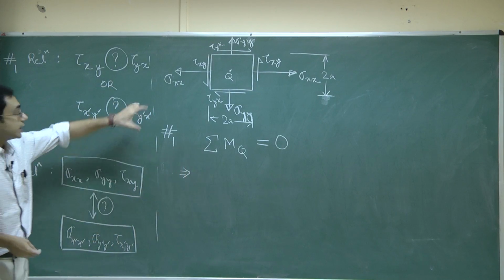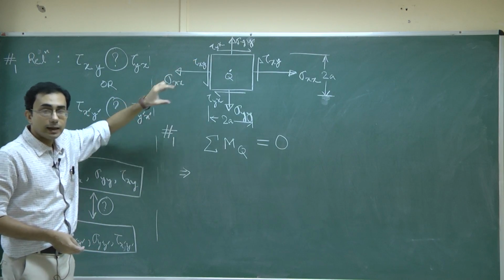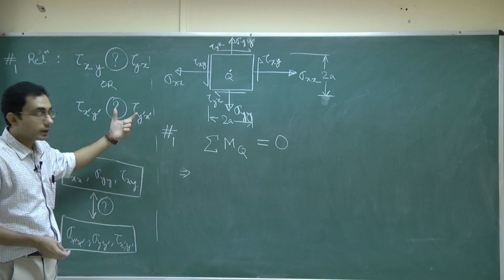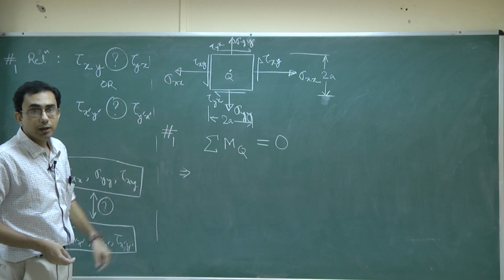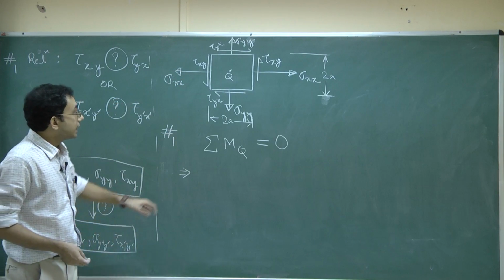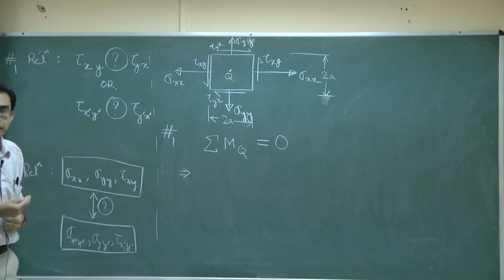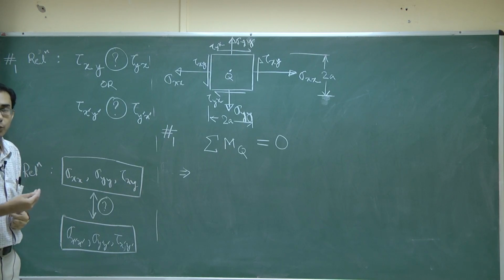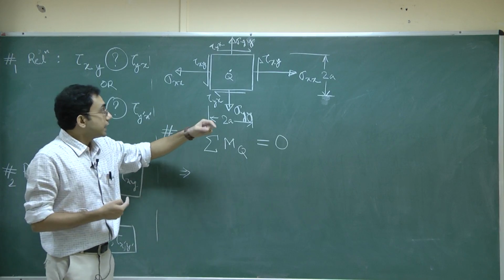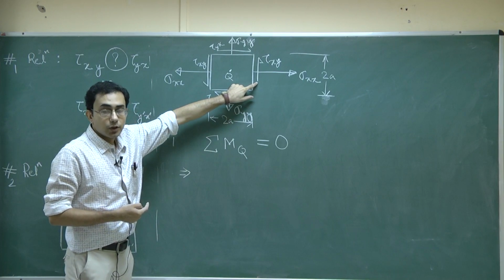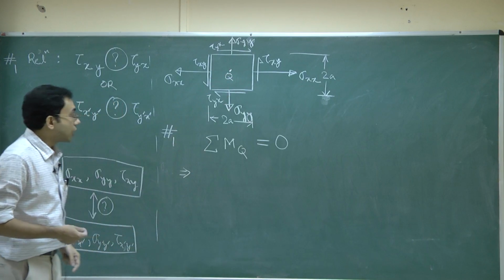Now you note that when I am considering this kind of a little square, which usually is referred to as a stress element, we might as well have called it something else, but we all call it a stress element. Nowhere here are we actually depicting a force, but you understand that each of these stress components is obtained by considering the limit of a force with a particular area. Now just as I can obtain this shear stress, for example, from a force, so also I can obtain the force back from it. So how do I do that?